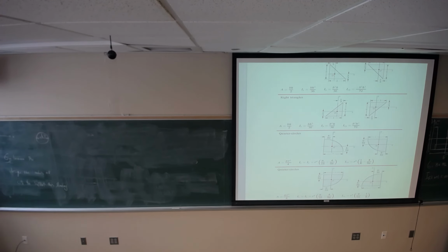So we have some load applied here. Due to this loading, we are going to have bending moment. Bending moment is making the normal stress. I should find the critical section, and then do the design based on that critical section. How can I find the critical section? I'm drawing the bending moment diagram.